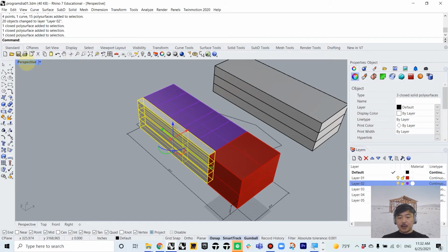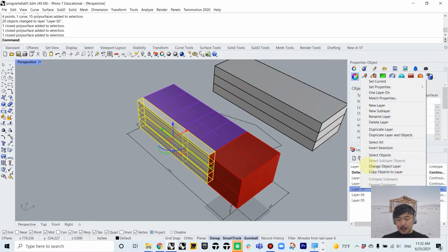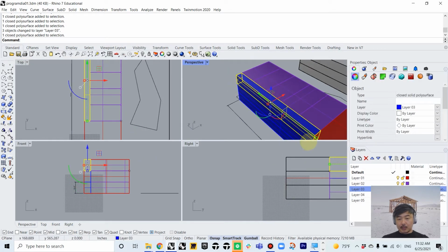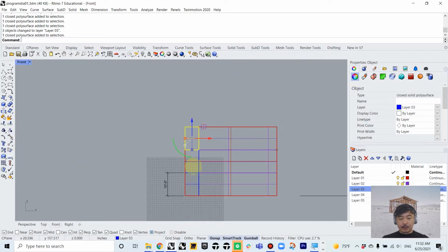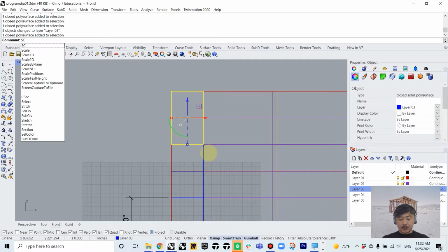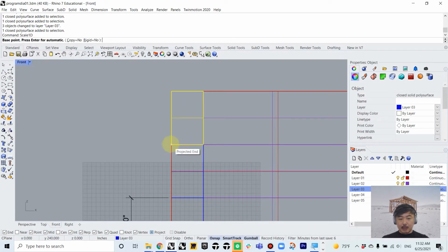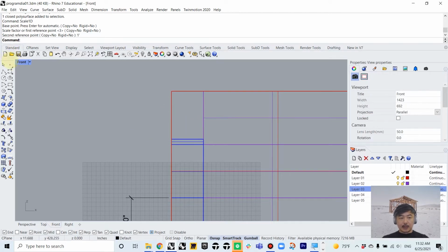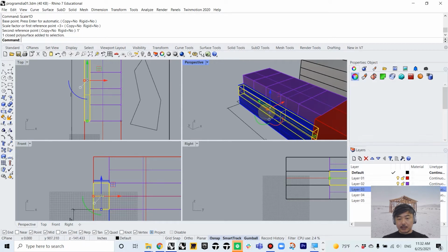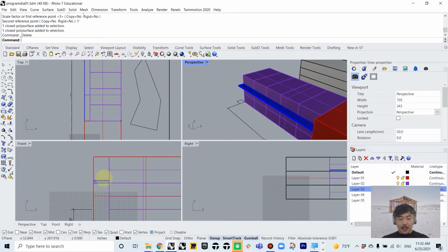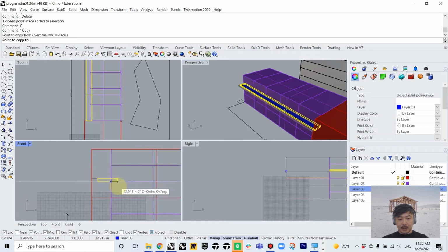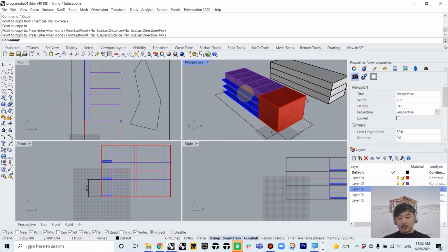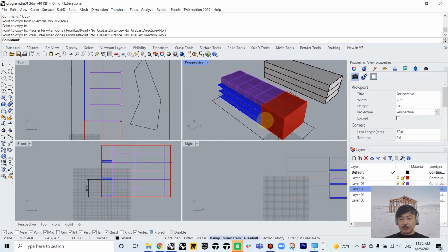So it's a hallway. So the way I am going to do is I am going to just make the hallway to be empty. So I am going to select this one and go to my front view and type scale 1D and then click on the bottom, click on the top, and just type 1 foot. Okay, so that's going to reduce the height of this place. So you can just copy this hallway down to second floor and then first floor. So that's a pretty good decent volume.